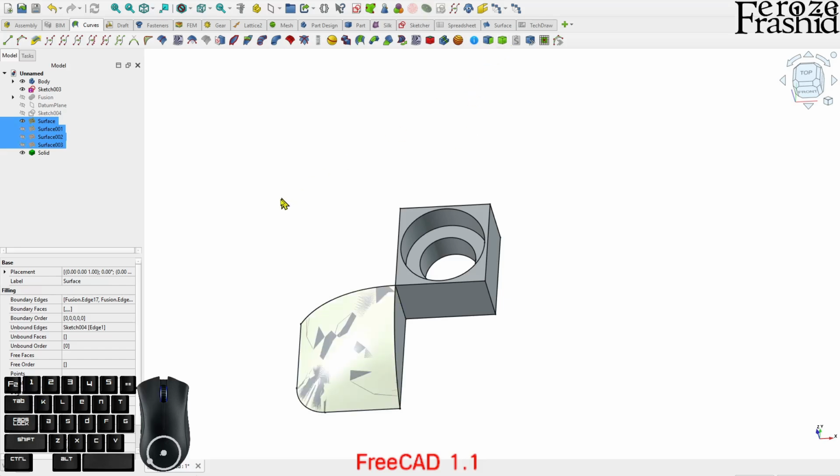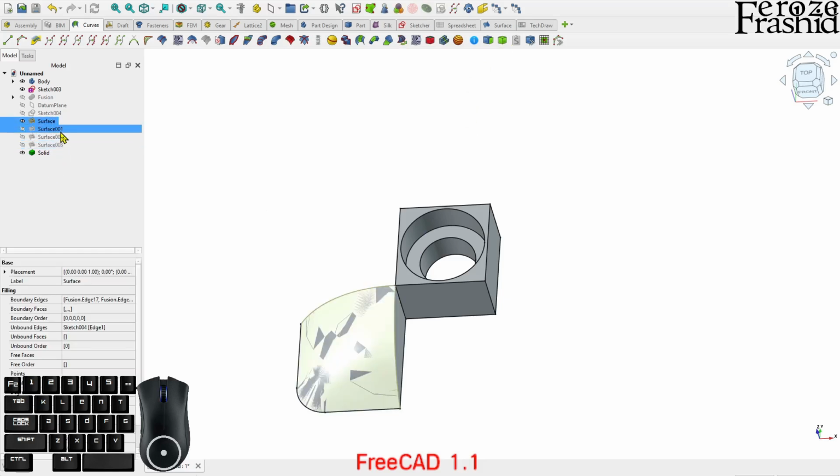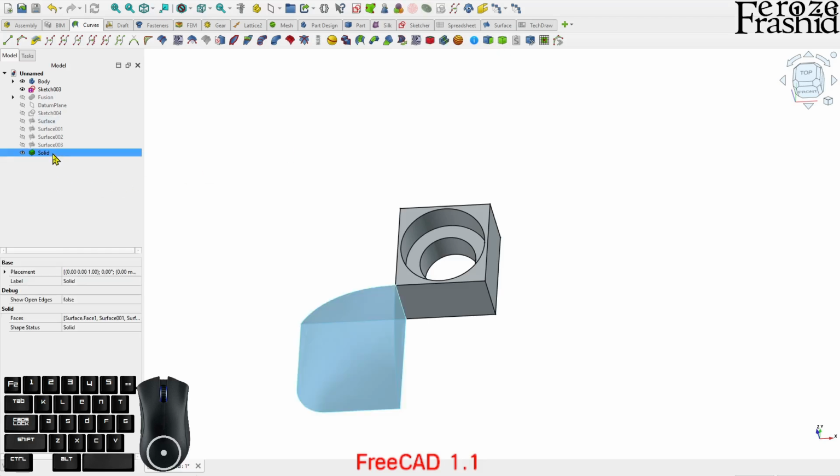So okay, now you can see, all right, there is a surface visible. I'd hide that. Now you can see the color of this solid is the same color as how it appears on the toolbar. That means that it is a solid. If it came in as a grayish, like black instead of green, that means the solid did not form right.